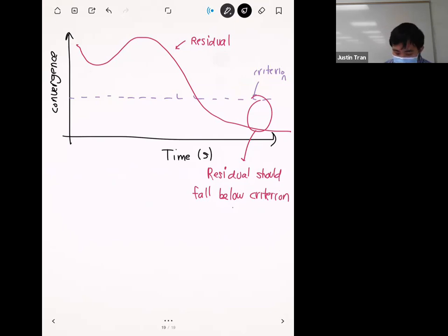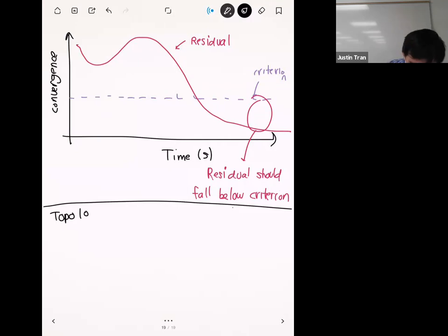Okay. All right, and so that's geometric nonlinearity, and that's how you can account for large deformations, and also check to see how well you're simulating those large deformations. And so the next source of nonlinearity is topology nonlinearity. Okay, and this strictly has to do with how you define the connections between parts in an assembly.